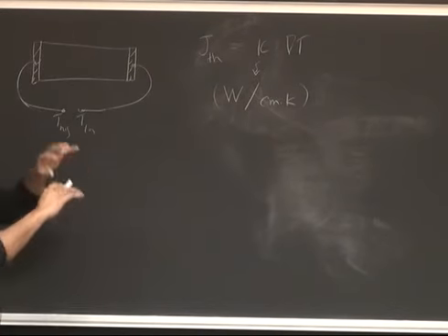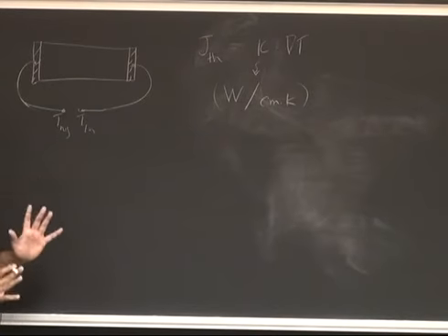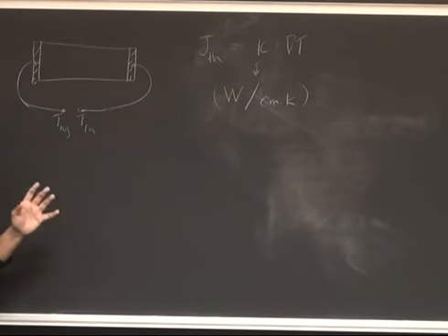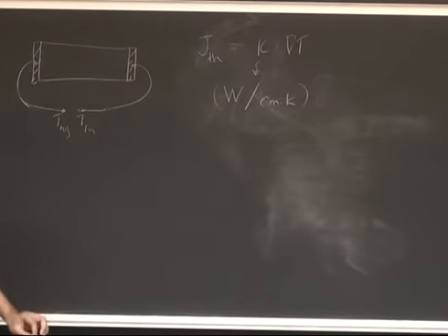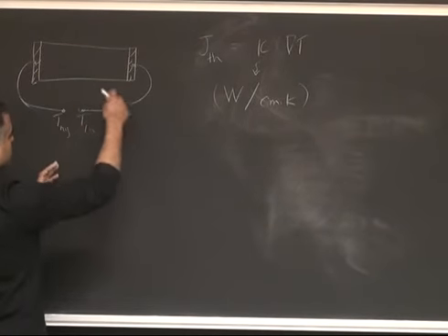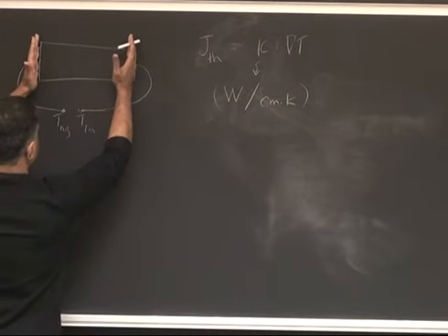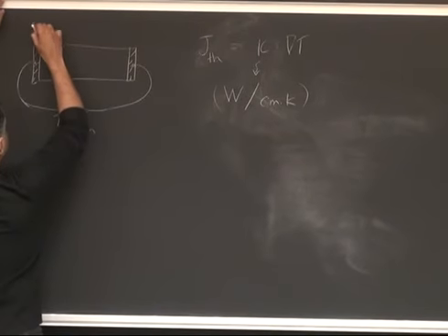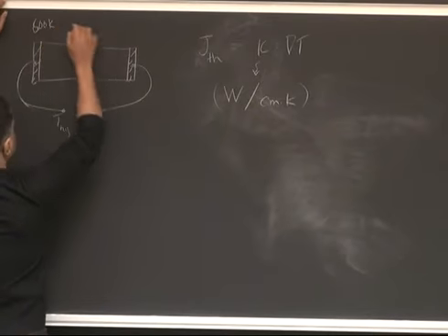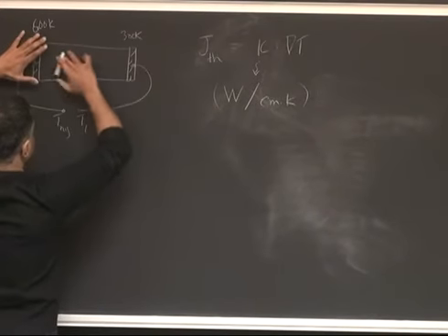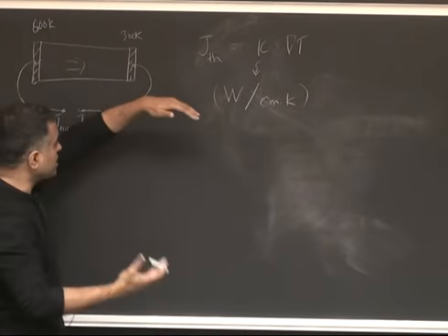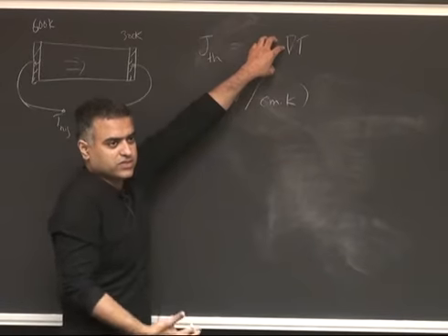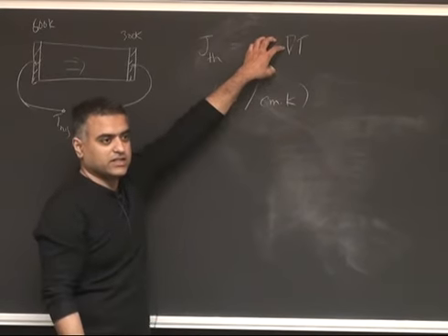And that's true for a three-dimensional object, three-dimensional semiconductor, amorphous material, whatever, right? So it's three-dimensional. That will be the units, watts per centimeter Kelvin. And people have obviously done a lot of experiments on various materials, where you maintain maybe this side at 600 K and this side at room temperature, and you see how much energy flows across. By changing the temperatures, you can measure this, just like you measure Ohm's law and electrical current, right? You measure this as well.